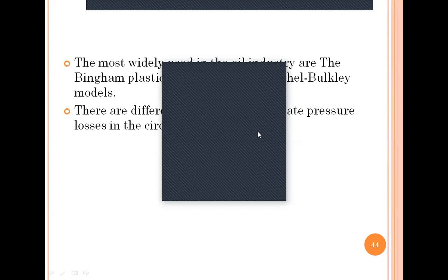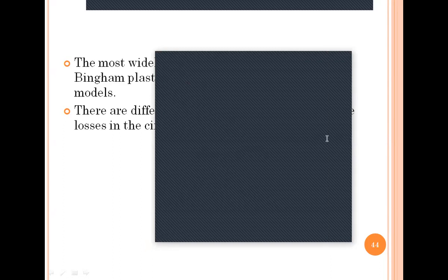There is another question here. How to assess the pore pressure having only seismic or logs data? Most of the time, this is not provided to us as a service company. This is for the operating company that has the seismic or the logging data or even the wireline logging. So as a mud engineer, I'm just dealing with what I get from them, but I know how they got it. They got it most of the time with wireline logging, and also PWD, pressure while drilling. We can calculate this pore pressure.